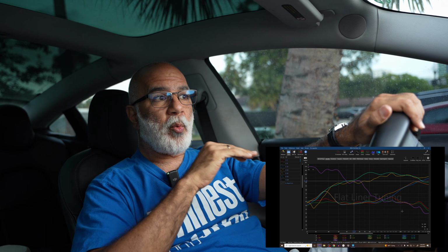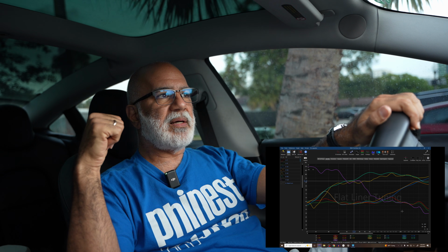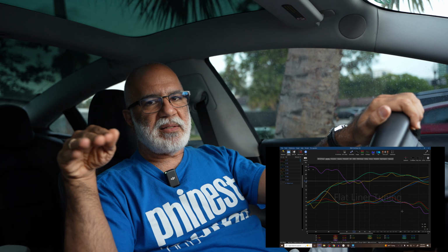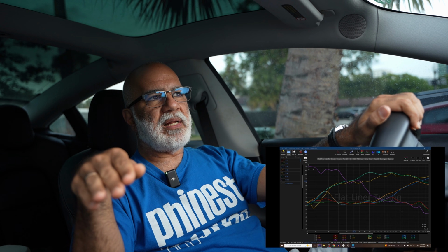The speaker that is furthest away is my subwoofer, but I'm not going to do time alignment using my subwoofer as a reference. I want to use my right mid as the reference, and we're going to align my front stage with the impulse response and the subwoofer with the phase alignment, which I think is going to be easier for me to do that way. And that way you're going to know both.